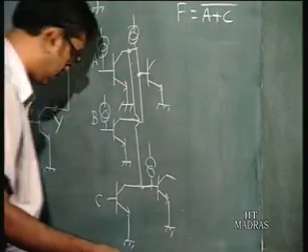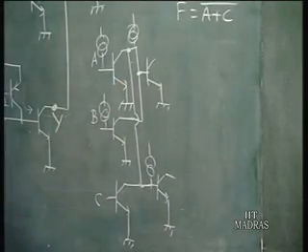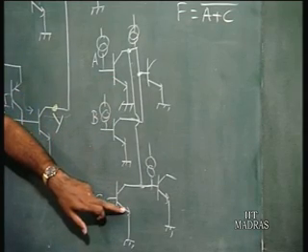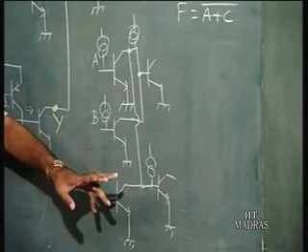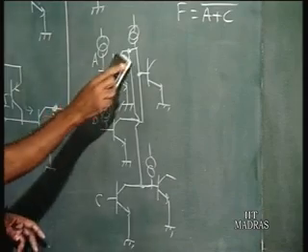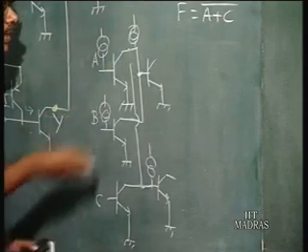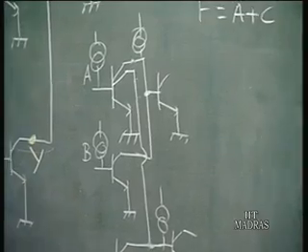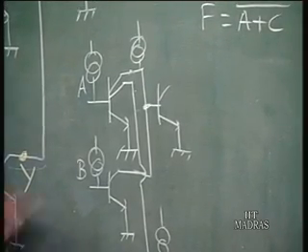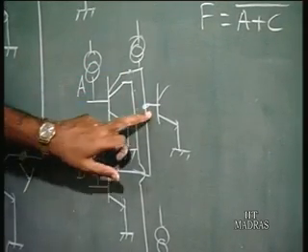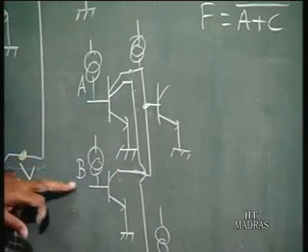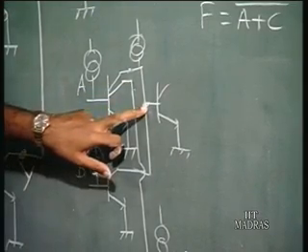So that is the problem. You have basically shorted all the 3 collectors. So, you have a 3 input NOR gate. So, what you have to do is have a multiple collector like this and coming here like this. In that case, here you have shorted the collectors of these 2 transistors whose inputs are A and B. So, this is NOR of A and B.